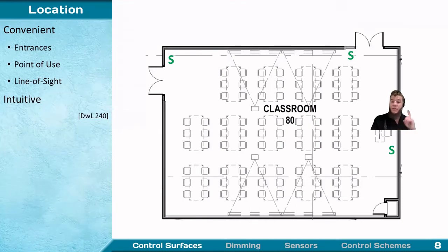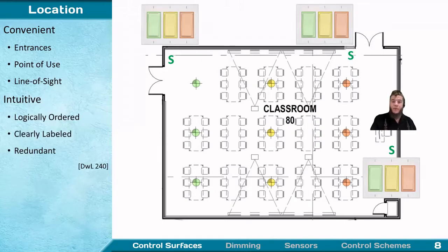and shout at me which switches she was flipping, so I could shout back what was happening with the lighting in the main space, because you couldn't see 75% of that space from where the switches were located. So you do need a line of sight to the fixtures. Now let's add on to this and talk about making a control system intuitive.